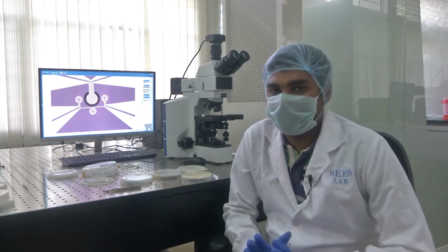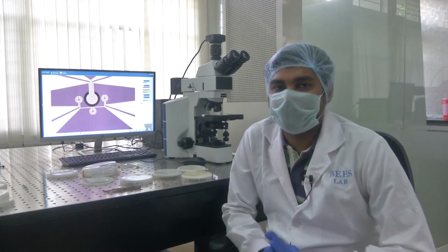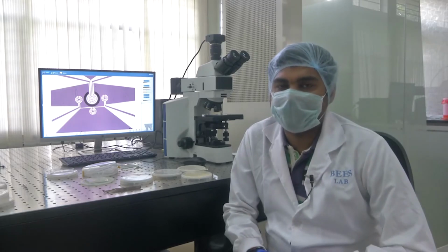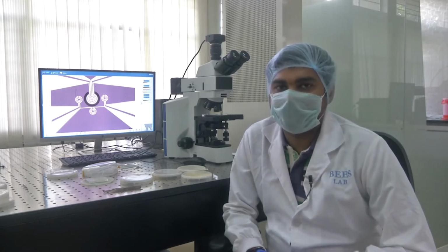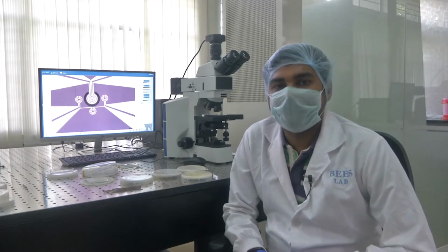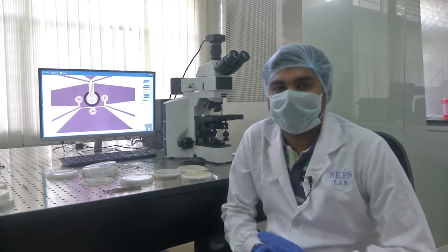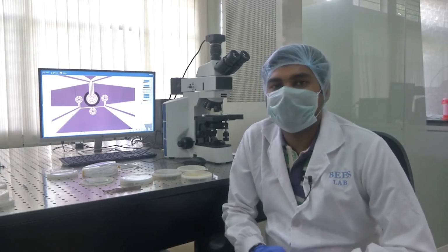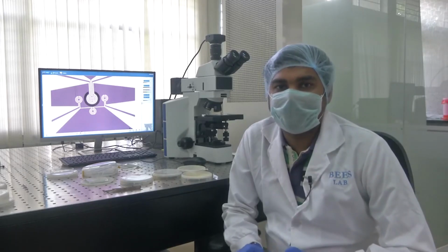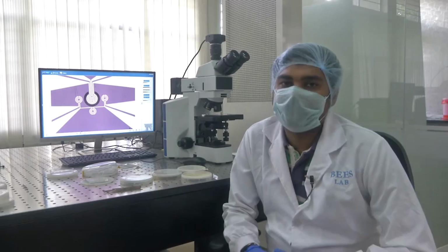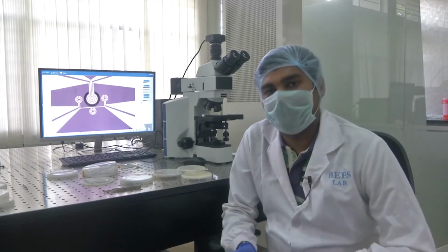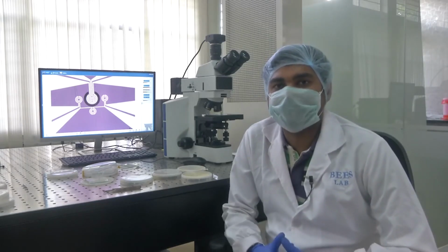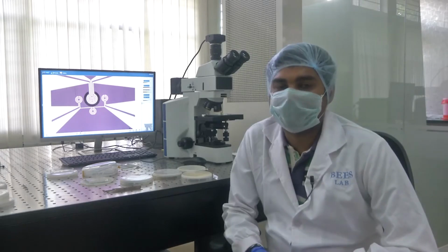So I have told you that the main process that is involved will be photolithography to pattern. Before that we will do some form of deposition, either e-beam evaporation or sputter deposition or thermal evaporation, and then after deposition we will pattern it, and then we will etch out the unwanted material from the wafer. The wafer or the substrate may be silicon, glass, or instead of silicon wafer it can be a germanium wafer, it can be a PMMA substrate, it can be a glass substrate. A lot of different varieties of substrates are available.